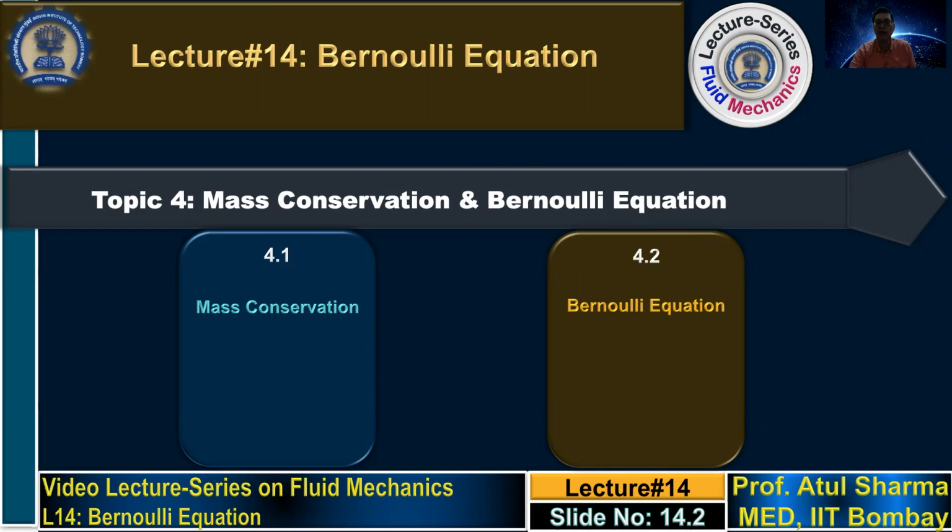When we talk about this law of conservation of mechanical energy, we take situations where the compressibility effects as well as the viscosity based frictional effects are negligible. Although this equation is quite restrictive as far as the assumptions that are being used, however, for many fluid flow situations, it is widely used as a powerful tool as it gives us certain limiting values for various engineering applications.